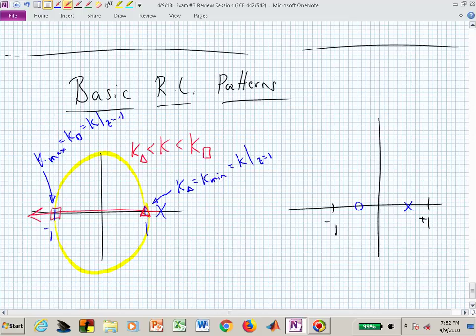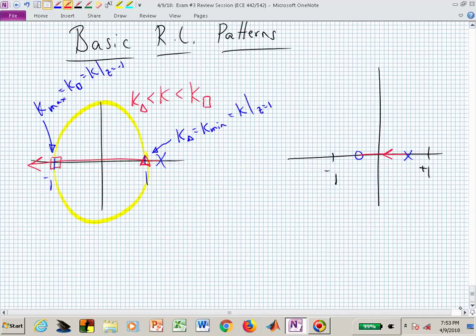And the root locus, you now step on one of those 3 segments, look to your right, and look for an odd number of poles and zeros to your right, and you're increasing as you move from poles to zeros. The arrow is now pointing to the left. What values of gain K satisfy this system stability? All of them, all of the non-negative values of K. K from 0 to infinity stabilizes this system. That's a trivial system, isn't it?